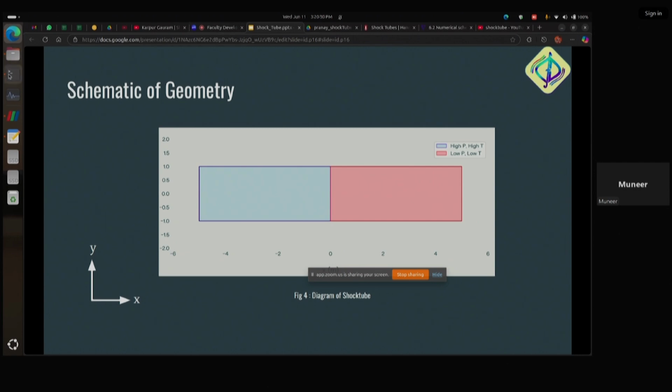I was just saying that the initial setting means that whichever solver we are using, it is at the first iteration, right? So at T0 or first iteration, it is starting with values like 10,000 Pascals. Then for all the cells, like 25,000 cells, including the inlet, outlet, the high pressure and low pressure regions, for everything it is set to 10,000 Pascals. Not everything, it is region wise. For the high P part, it is 100,000, and for the low P, that is the red region, it is 10,000.